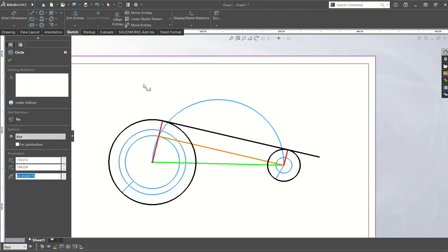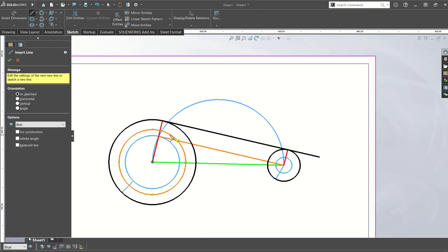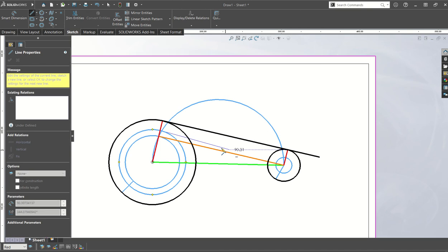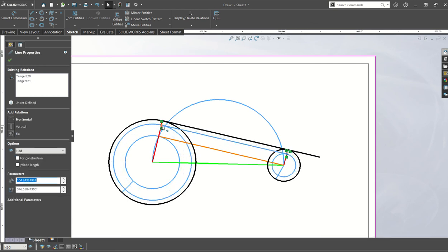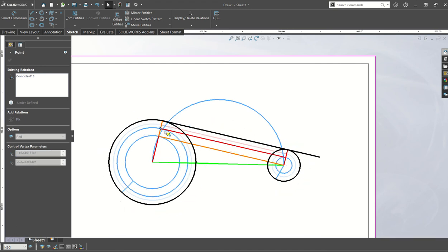This is the one that moves, so I just need to select a point on that circle to draw a point on. So my beginning point is there, and then the point on this, which I can draw, and then that has automatically selected them to be tangential. Now, the reason that it's going a bit crazy on me right now, and the reason that it's not working out, is because my tangent is not parallel to the original tangents that I'm using in my question. So what I need to do is select this, so it is right now, but I'll just change it to make it clear that it not always is.